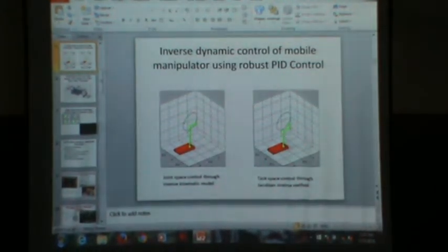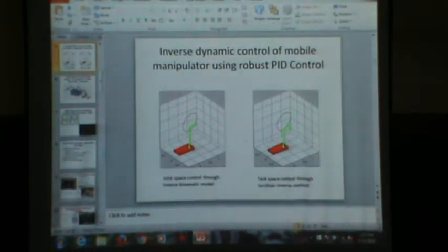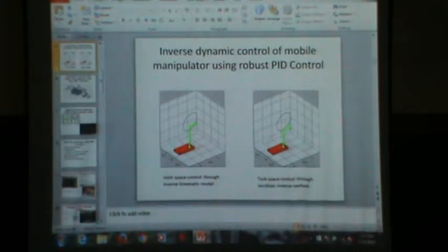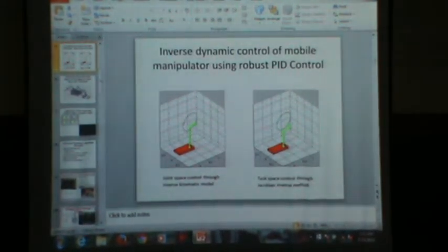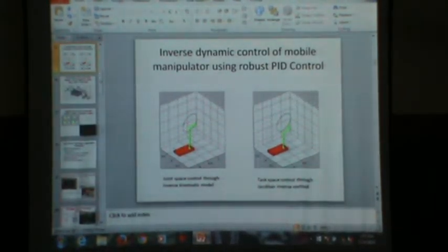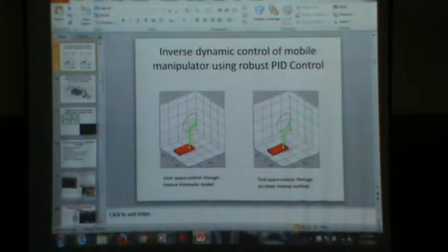So this point needs to be followed, and based on this it may go up and down. Now imagine this is faultily designed. This is also faultily designed. So how will your task-based control overcome it, or how will the joint-based control adapt? This particular error, the joint space will not overcome. Even people can say that okay, I can use a kinematic calibration method. I will calibrate every instant, so I will readjust. So probably this kind of error you can calibrate.